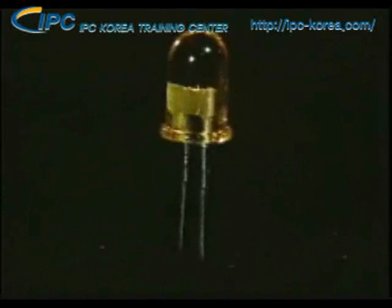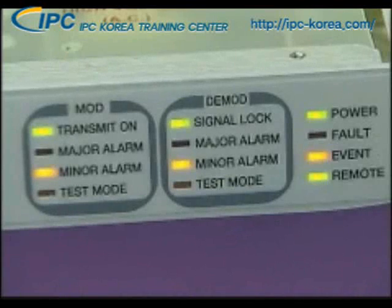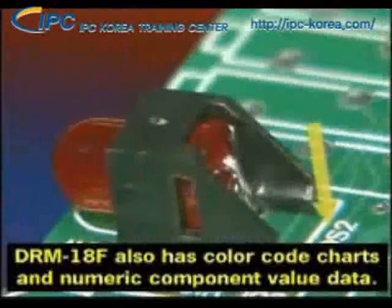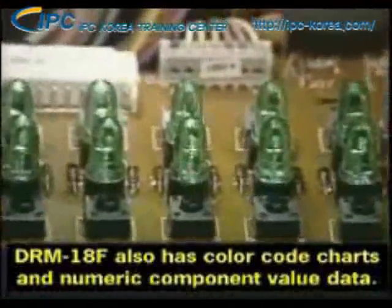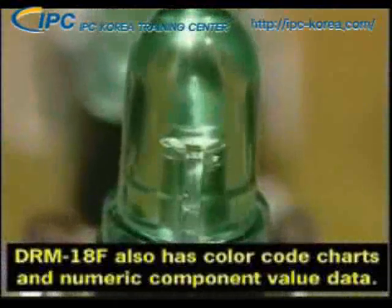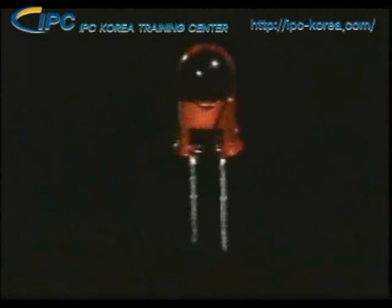Another type of diode is called a light-emitting diode, or LED. LEDs emit light and are typically used as display indicators on the front panels of electronic equipment. The reference designator for an LED is usually DS, although they may be identified by LED, or by the diode designators CR or D. LEDs usually have radial leads.